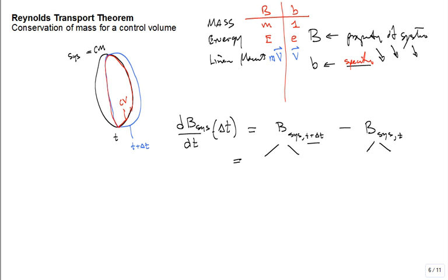And then they have all of this. What is all of this? I'm trying to show little vectors for fluid flow coming in, because at time t, all of this region that I just showed in purple, maybe we call it region 1, is not in the CV. But at the end of the time, it's going to be in the CV. It's all swept in. True?